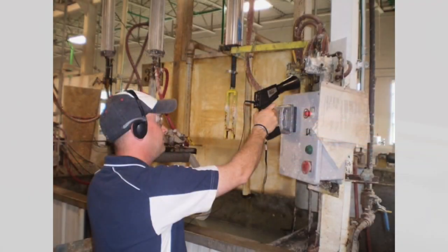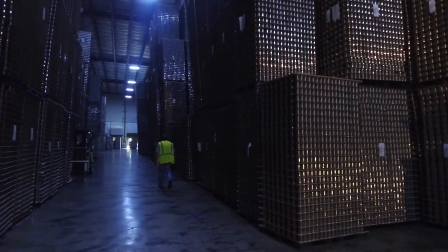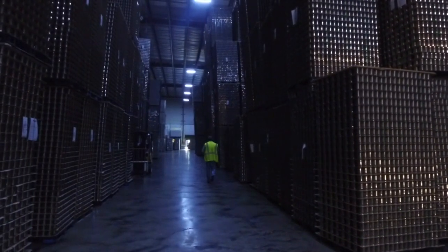A second, higher tech way is an ultrasonic air leak detector. These devices work based on the principle that ultrasonic noise decays very rapidly away from its source. Therefore, if you hear a large amount of ultrasonic noise on a compressed airline, there is most likely a leak present. These devices are sold at low prices, so it's a good idea to have one around to play with, but they don't always work well in loud manufacturing plants. However, if you're in a warehouse or another quiet location, this method is very effective.